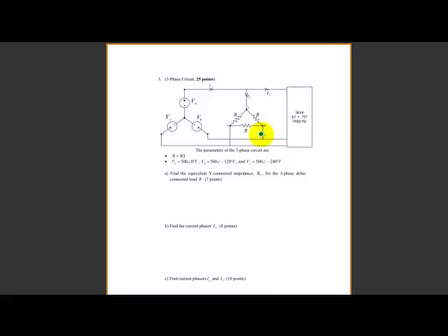If the voltages between the three phases were totally different, with different magnitudes and different angles, not 120 apart, and if the resistors were completely different values. But this is not the case. This is apparently a balanced system, as you can tell, because I have this R as the same value, which is the R value here, which is the R value here, which is 3 ohm, and then VABC is actually 500 volt with 120 degrees apart.